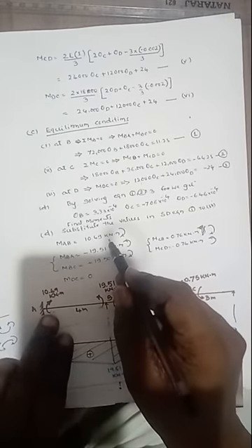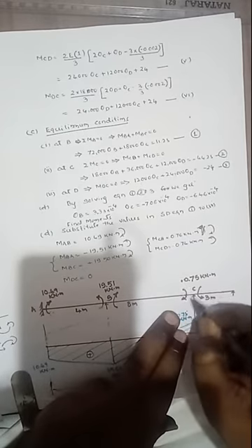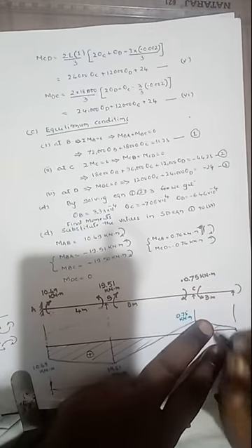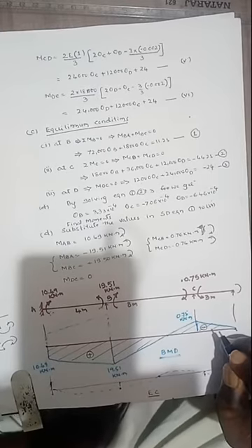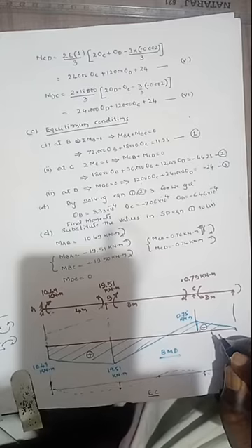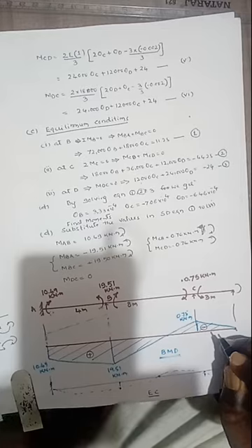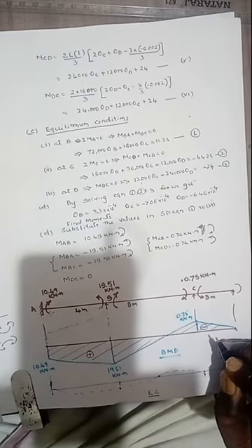Here the moment MAB is clockwise. Similarly MBA is anti-clockwise. MBC is clockwise. MCB is clockwise. MCD is anti-clockwise. MDC is 0, no moment at that end. Now we can draw the bending moment diagram. Here there is no simply supported beam bending moment, because the spans AB, BC, CD are not subjected to any load. Simply draw the support moment diagram.